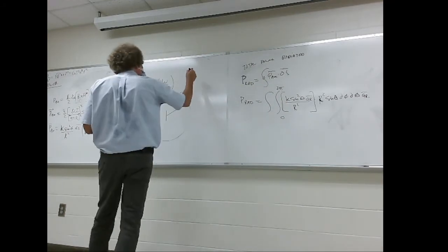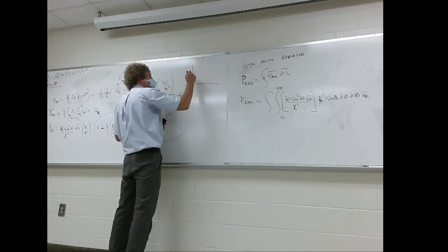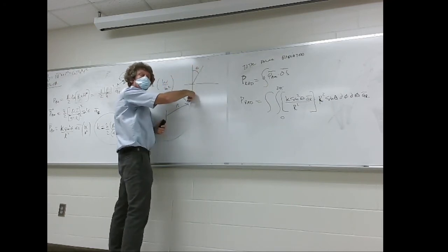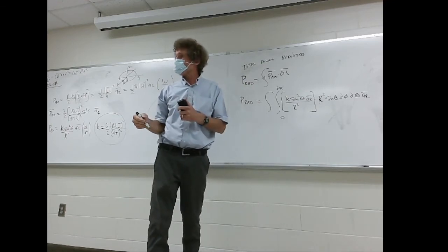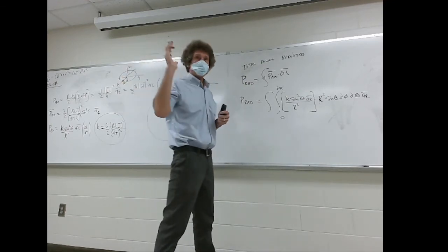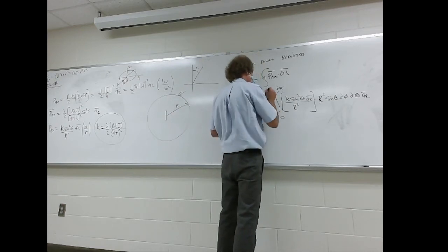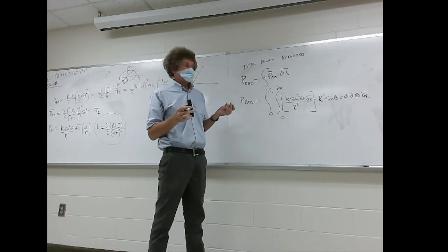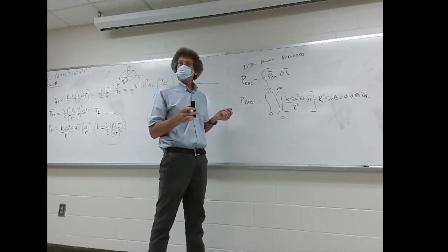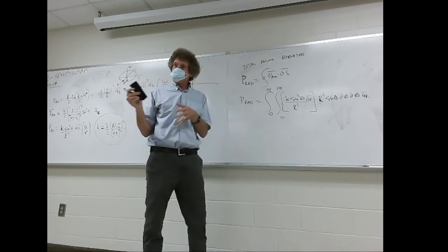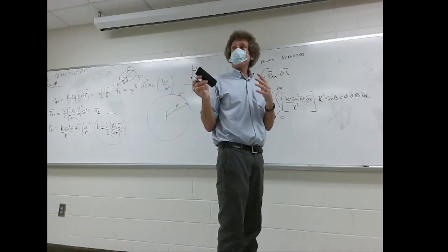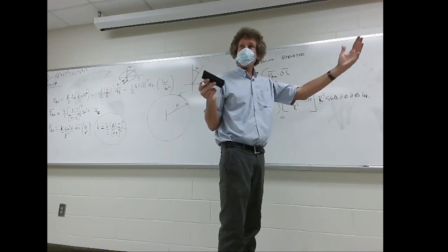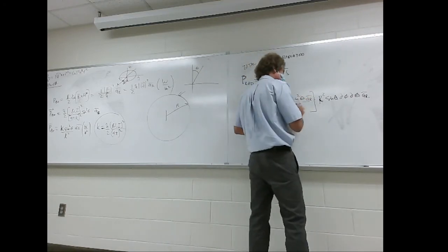Now, what about the vertical? Well, if this is theta, it goes from 0 to pi, right? Pi radians are 180 degrees. You with me? It's important, it really is. So it's from 0 to pi radians. Now, if we're doing this integration, does anybody see what cancels right off the bat? The R, yeah, and if it doesn't, then you made a mistake, because the total radiated power cannot be a function of how far away you are. Unless it's a lossy medium, but this isn't. So we just get rid of this R squared, thank God.